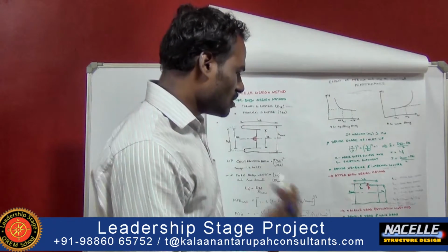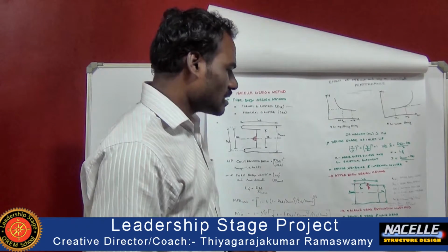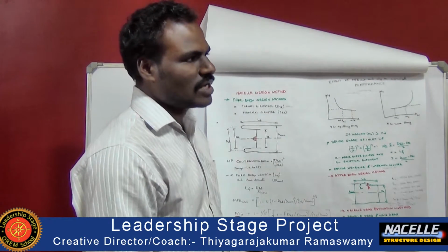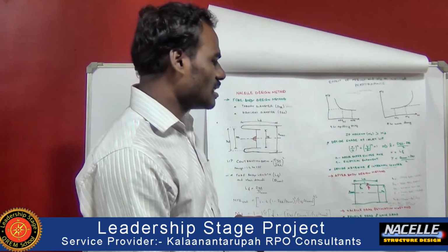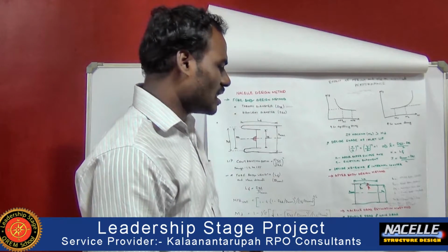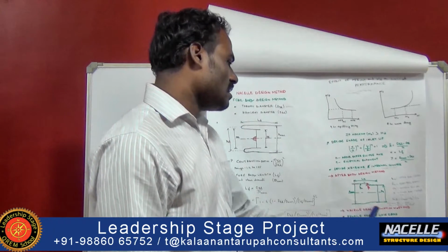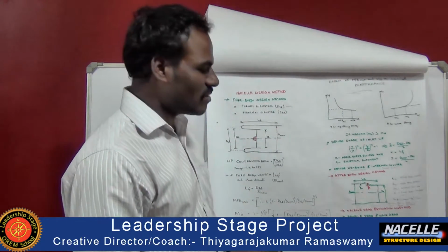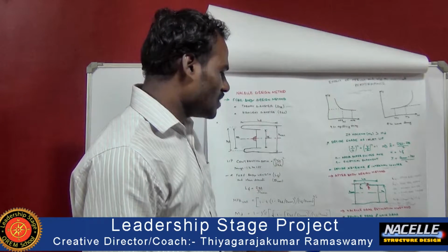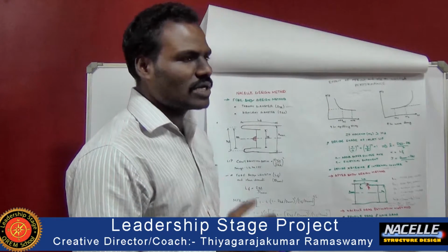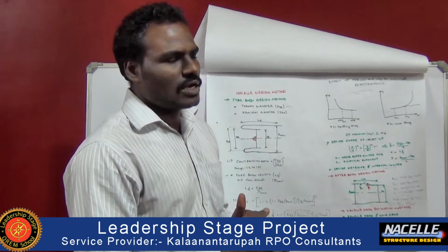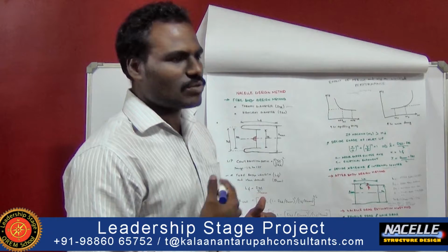And now next we are going to discuss the nacelle drag estimation method, which helps us in reducing the drag of the nacelle as well as the aircraft, for better performance of the aircraft. Here, the nacelle drag is estimated with respect to the profile drag as well as the wave drag. This nacelle drag will be tested under the conditions of wind tunnel as well as CFD processes.